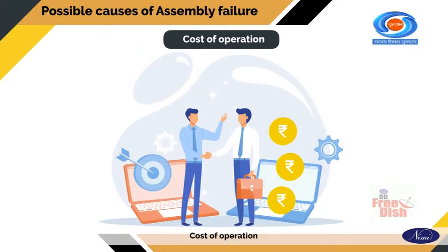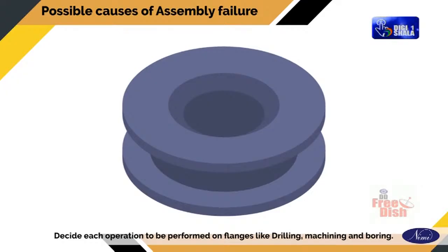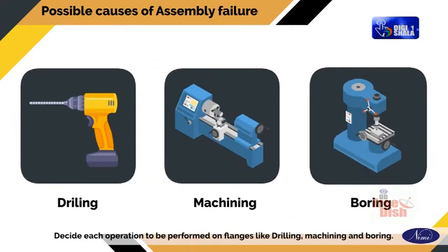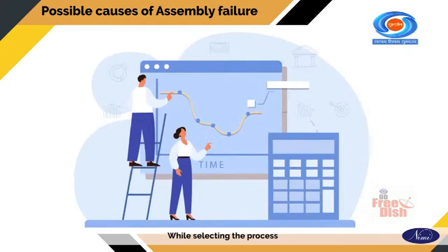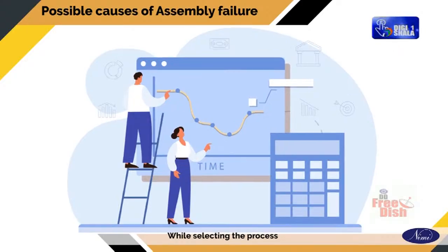Cost of operation. Decide each operation to be performed on flanges like drilling, machining, and boring. While selecting the process, do take care of sequence of operation as it matters a lot on costing.